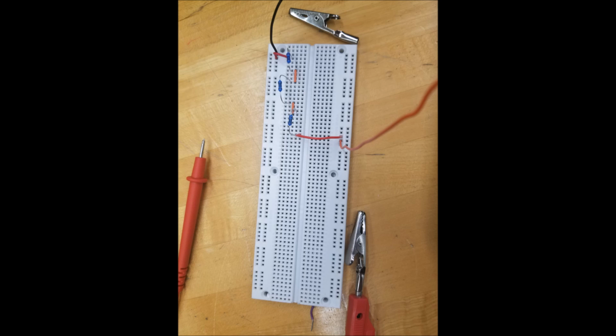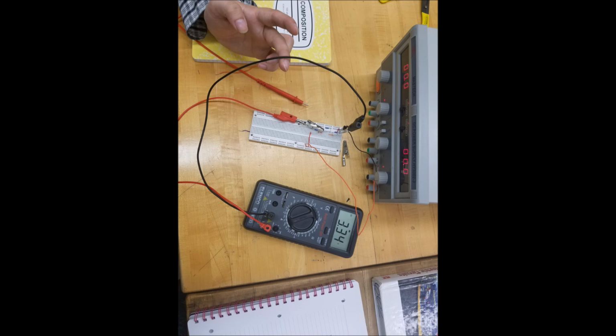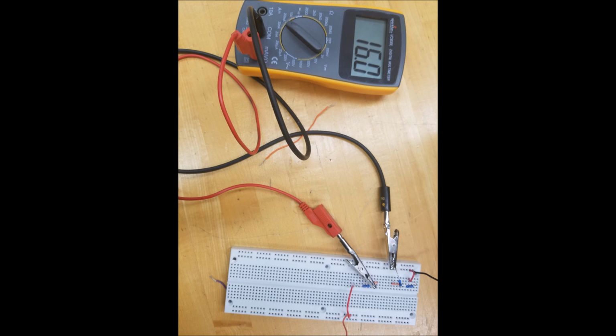You can see the way that we've actually put the circuit on the breadboard is the 3 resistors right below each other. Once our circuit is hooked up to the DMM, you can see that it has 5 volts running through the entire circuit. The first 2 resistors will have 3.34 volts running through them, and just the first resistor will have 1.67 volts.